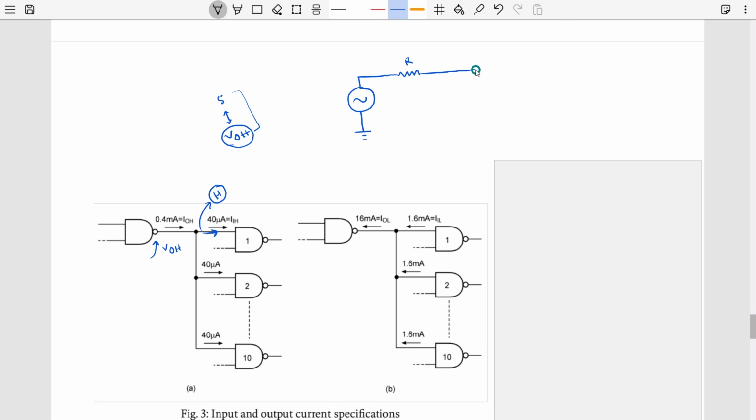And then, to represent our home, we can use one load. We are just drawing power, right? So maybe this is a kind of resistor. I am using the most simplistic explanation, but basically it is drawing current, right? That current is coming from the substation. Whatever current is flowing inside our household, that current should also go through this transmission line, and because of that, multiplied with R, this amount of voltage will be dropped through the transmission line.